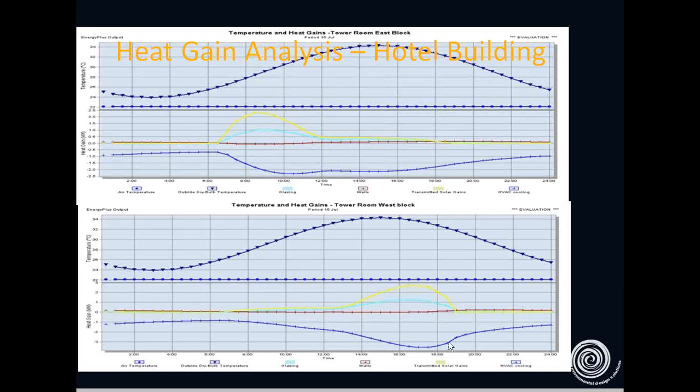So there is a diversity and there is something you can offset. So actually you need not double for your central plant sizing. You can take around 75% of this load and do that. So it's a non-coincident load that helps. Then the simulation tool also helps you in doing the load analysis in various months. What is the cooling load, hourly cooling load.